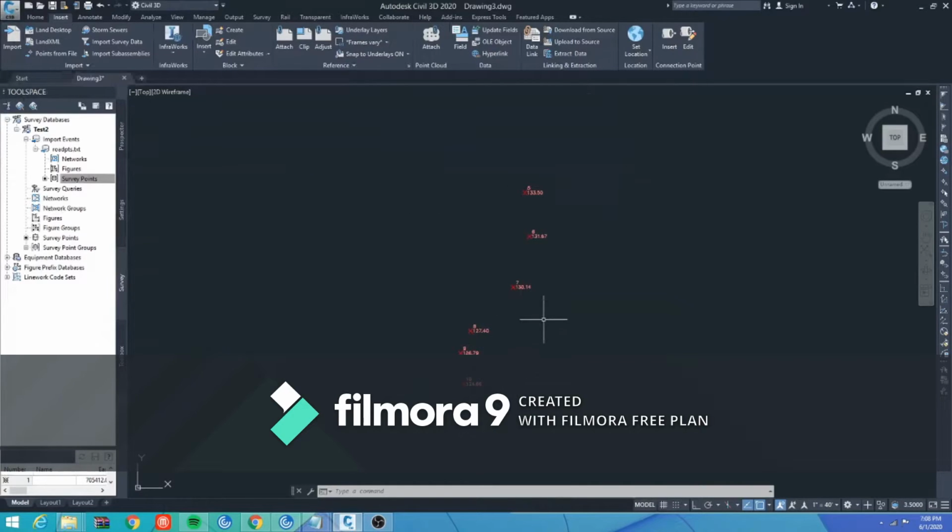So this is a relatively small file. We have about 10 or 12 points. However, some projects can have 50 points or over 100 points, and it might be hard to distinguish them. For example, we can have points that describe a road, as well as points nearby that represent rivers, and we want to divide them into two different groups to distinguish them. An easy method to do this is by creating point groups.